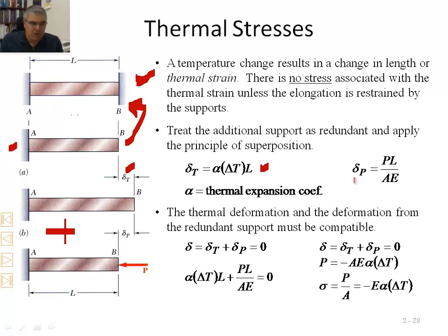Also, last time when we talked about strain in previous lectures, I defined strain as such, and we developed an equation in which the stress and the strain were related, and the displacement or elongation was related to P, L, A, and E. Remember, E is the Young's modulus of elasticity, or simply modulus of elasticity.